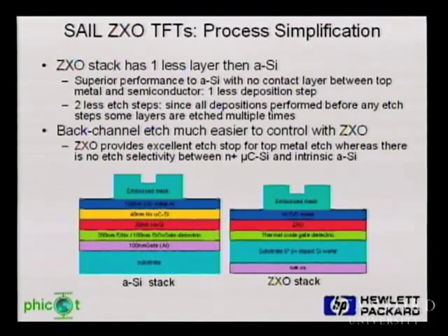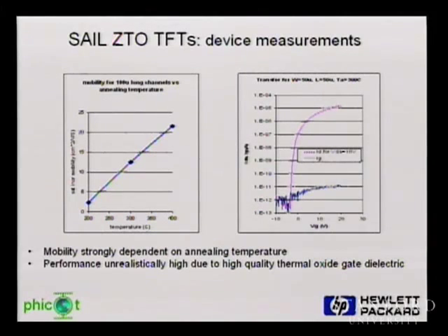And in the case of these zinc oxide-based materials, in order to get a good ohmic contact, we don't have to have a degeneratively doped N+ layer, and we can just directly put a metallic contact on them. And by getting rid of that layer, it really makes a big difference on the cost. So we have made those with this same process. We're not at the state that we are with amorphous silicon in our deposition capability, but they look very promising, and we really think that's going to be the next step for us.